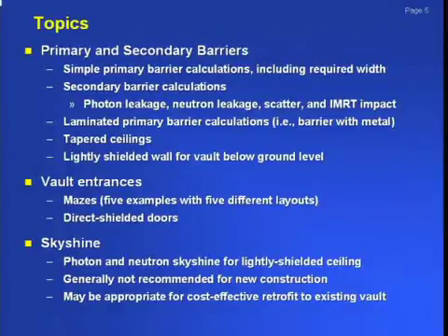What are the topics we're going to cover today? Well, obviously, these are the different areas you have to consider when you're generating a therapy shielding design. You must consider your primary and secondary barriers. You must consider your vault entrances, and you must consider sky shine if you do not have a primary barrier.